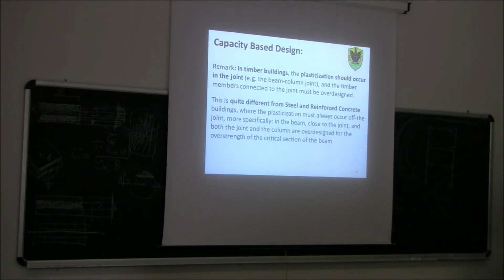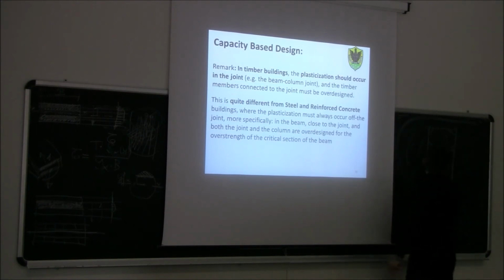So this is the kind of structure with plastic behavior. If you want, you can assume that the beams and the columns don't plasticize, so they remain elastic. They are pin connected. However, here there are some rotational springs.